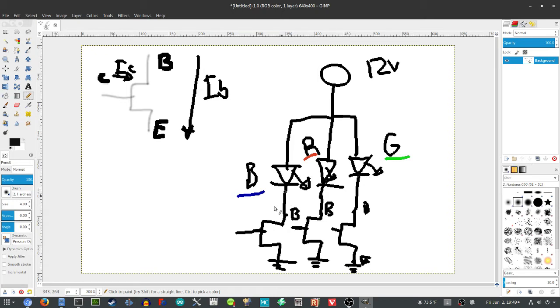So this you can actually switch with the Arduino on the RAMPS. You can connect it to the servo pins that you have at the side of the RAMPS, and then you can switch these three. So basically you can give a G-code which you can put in the firmware, and then you can switch this depending on what your printer is doing.